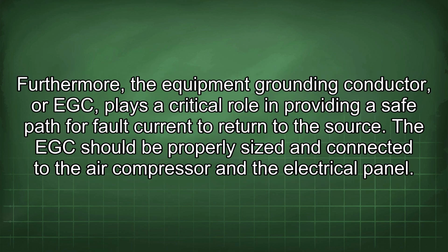Furthermore, the equipment grounding conductor, or EGC, plays a critical role in providing a safe path for fault current to return to the source. The EGC should be properly sized and connected to the air compressor and the electrical panel.